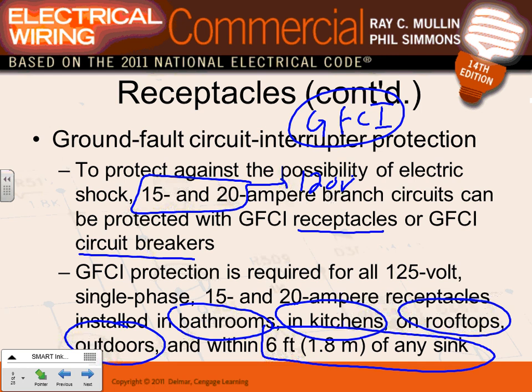Is it bad to put a receptacle for maintenance in a mechanical room in a GFCI? Is it a violation of the code, even though it doesn't say you need a GFCI in a mechanical room? No. Is it safer to put a GFCI receptacle in the indoor mechanical room where you have all your mechanical equipment that you're going to work on? Yes. So even though it's not saying GFCI is required, it's a good idea to put a GFCI receptacle there. Any question, guys, about the GFCI?